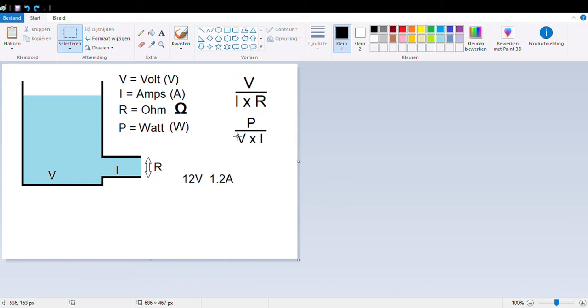As far as power consumption, that's what's appearing on your energy bill. What is it going to cost me? So let's see. I'm going to put the power consumption in front, like this, and now I can calculate how many watts it is using. 12 volts times 1.2 amps, 14.4 watts. For our convenience, it's going to be 15 watts. Your bill is like in Europe, at least in the Netherlands, we pay like 20 or 25 cents for each kilowatt hour.